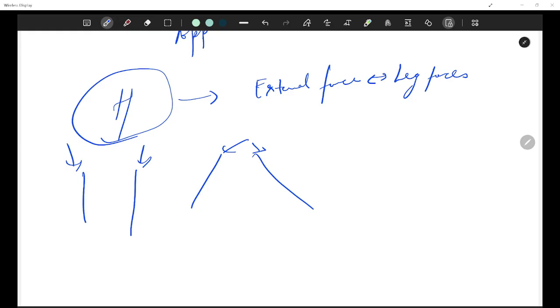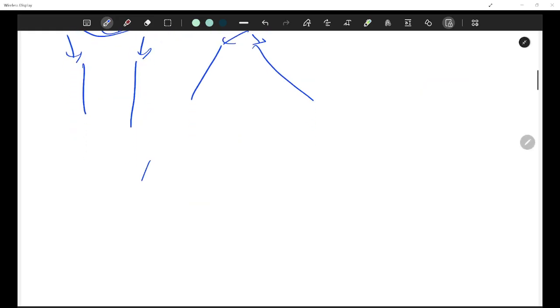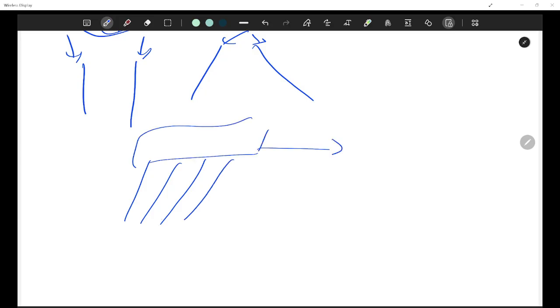Okay, then let's talk about singularity. What does singularity mean conceptually? The system loses the stiffness in some direction. For example, if all the legs become parallel, the platform can move freely sideways, but it is bad for motion control, right? But for sensing, near singularity, small external forces produce large internal leg forces, which gives amplification. So singularity is bad for motion, but it is good for sensing. All right, so it is a very important insight.